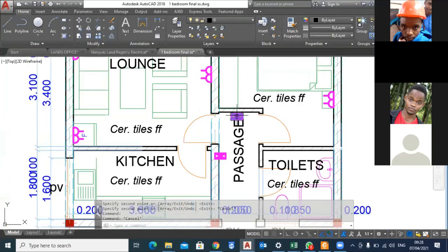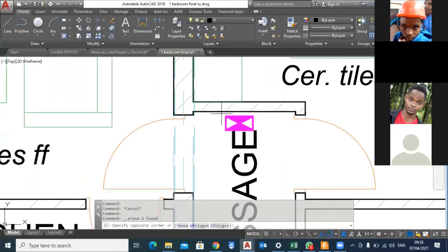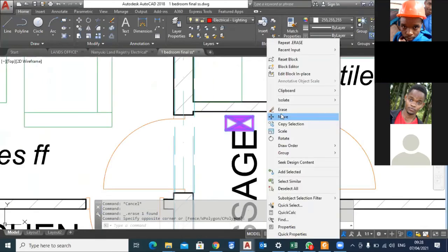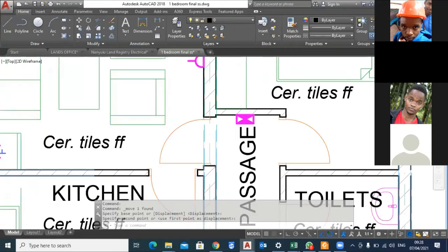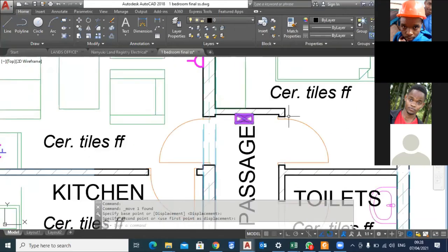So the most ideal place is either this place or this place. But the old logic some people have, that the consumer unit must be in the kitchen, is outdated. You need to put it centrally so that all the loads are distributed evenly, and it will also save on the amount of cables.